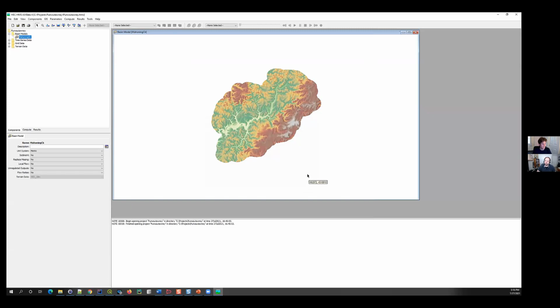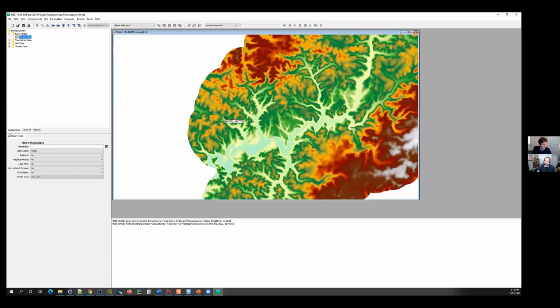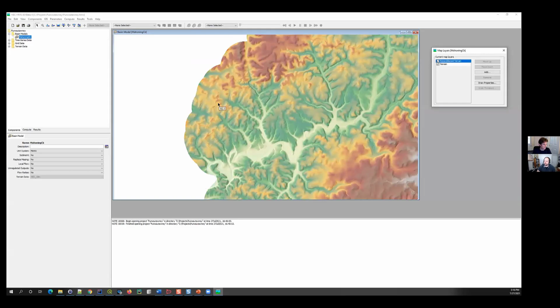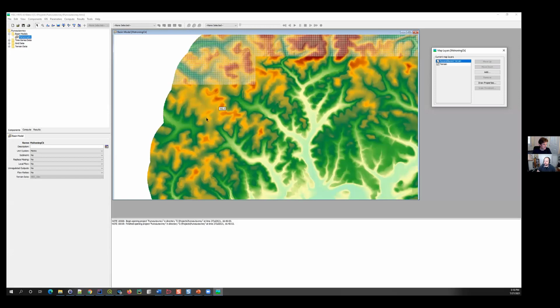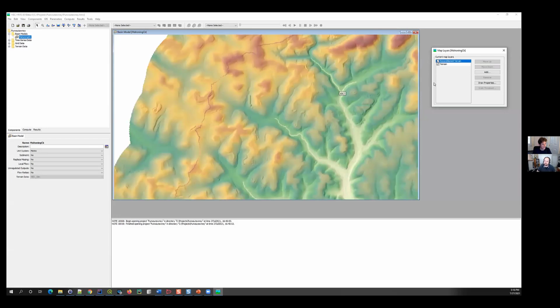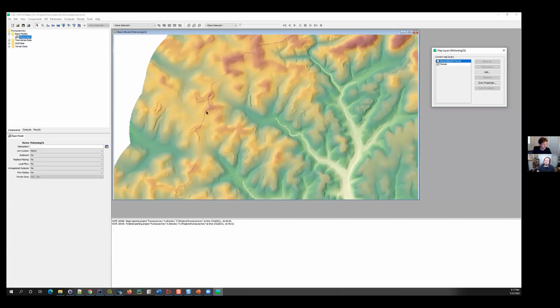Okay, reconditioning complete. Now to show you what has happened to our terrain data, the reconditioned terrain layer has actually rendered in our map display. I have our map layers here. So I'll just zoom into the boundary of the watershed, and I can already tell that the cells around the boundary look a little different than they were previously. Not sure if you can see that, but I will just toggle the reconditioned terrain on and off, and hopefully it becomes apparent where that wall has been built.